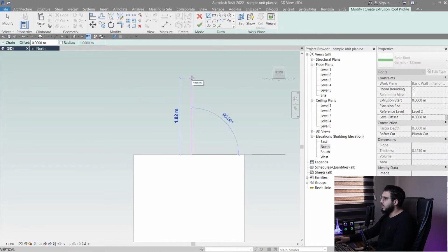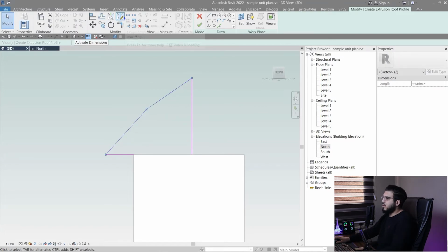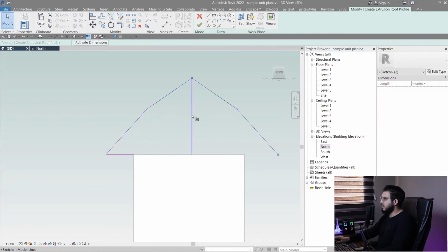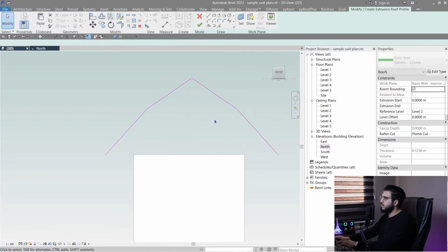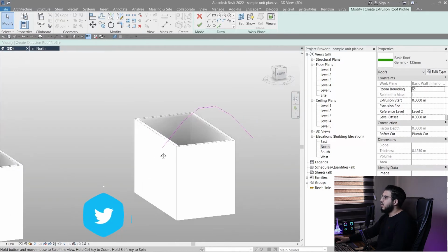Let's create a middle line, and let's bring a hang in here, and let's create our gable roof, or maybe I am pronouncing it wrong. And let's create a mirror at the middle of this one and click on in here, and let's maybe do something like this. Click on trim. I'm going to show you that every kind of profile is possible with this method.